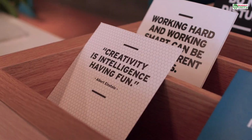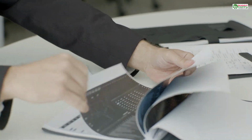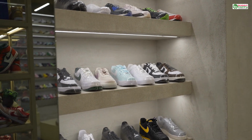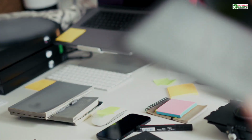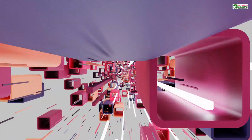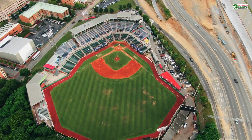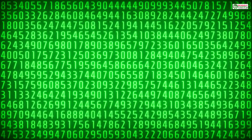Finally, after you upload your file, pay close attention to the information the website gives you. It will almost always show you what it thinks the final dimensions are. This is your final sanity check. It will display something called the bounding box, an imaginary cube that perfectly contains your entire object, and lists its dimensions in X, Y, and Z. Look at those numbers. Do they make sense? You wanted a coffee mug. Are the dimensions roughly 95 millimeters tall and 80 millimeters wide? You wanted a keychain. Is it in the ballpark of 50 millimeters by 30 millimeters? If the numbers look wildly off, you know you have a scale issue and you need to go back and fix it before you click Order.